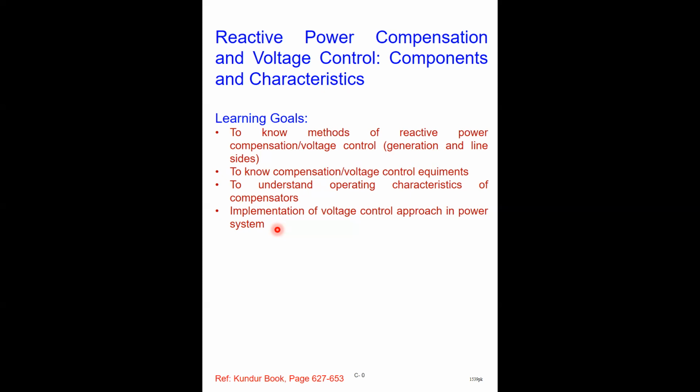So now when you have a distribution network integrated with renewable resources, we have regulations from the system operation side that these renewable generation resources should in some way be able to provide some amount of compensation and thereby contribute to voltage control in the network.